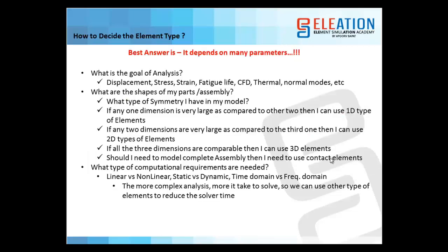Then the next question that arises is how we can decide the type of elements. So the best answer depends on many parameters, like what is the goal of the analysis, what exactly you want as an output. So if you want displacement, stress, strain, fatigue life, CFD, thermal, normal modes.